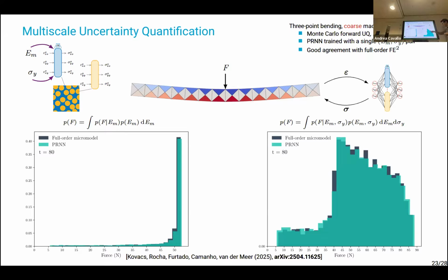That's what you see with these histograms. This is the propagated uncertainty. For this beam, you can see the finite element mesh here is very coarse, right? There's not a lot of elements. If I went to an engineering firm and showed this mesh for a beam, they would kill me on the spot. You should not do this. The mesh is terrible for bending. But we did it to compare the histogram, right?